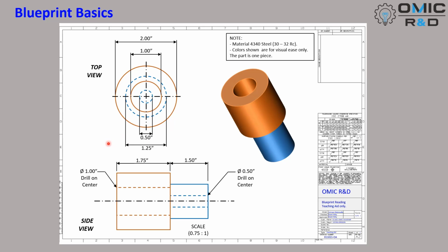And it should be pointed out that I'm further giving some more details in the lower print here by saying that I want these holes to specifically be drilled out, and also I want them to be on the center line of the part. And these are more details that we provide to manufacturers to control things like concentricity and runout.